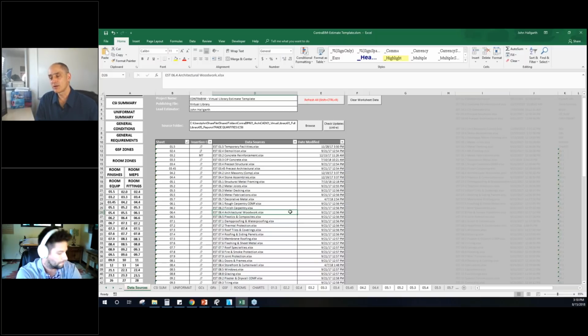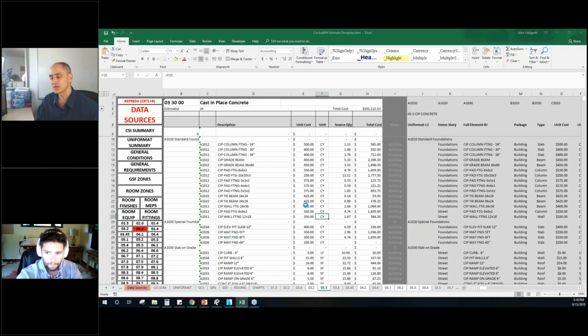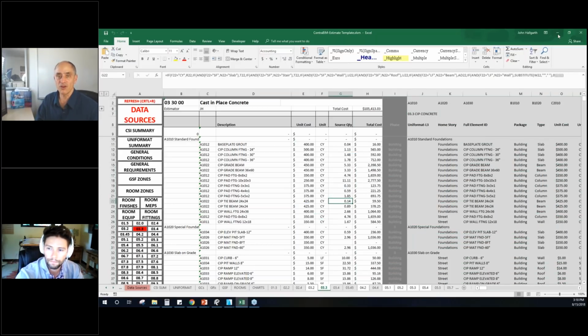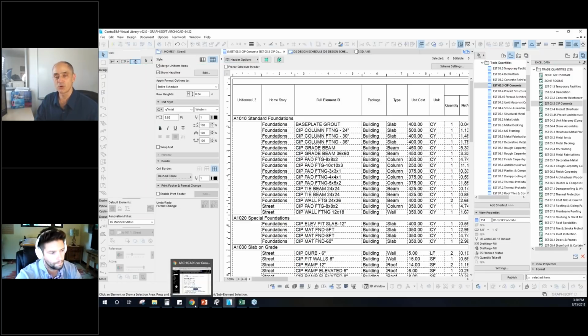Very briefly, the things that I've felt over the years is that ARCHICAD is more graphically oriented, so you can just visually in 3D views, perspective views, make changes much more easily. In Revit, often you have to go into dialog boxes, and for things like changing the size of a window, you may have to create a whole new family of windows, as opposed to just stretching it to line it up with this. Those are some of the things.